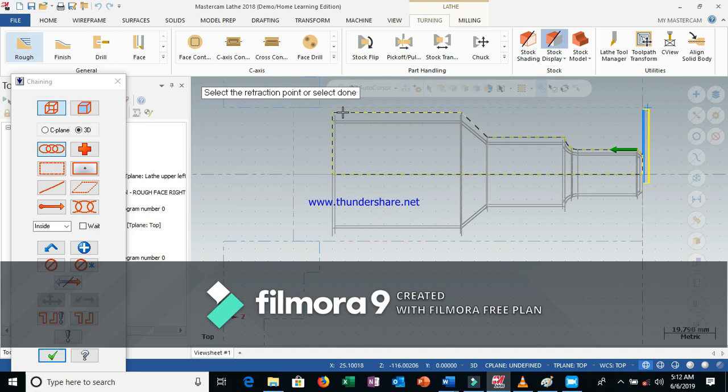Okay. Now select this line. So select this. Yes, simply click. Yes, click there. So the arrow mark has to show like a cycle, like a starting and ending. Yeah, you can see now. So this is after facing, it has to start from here and it has to end here. Yes, click. End means it will come like a loop. How many passes you will make, that much it will make.